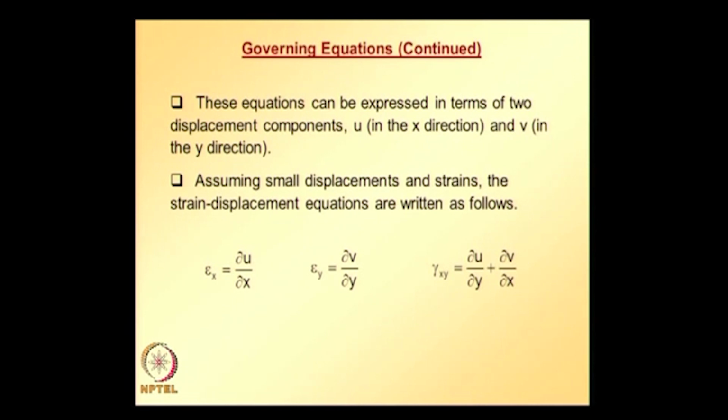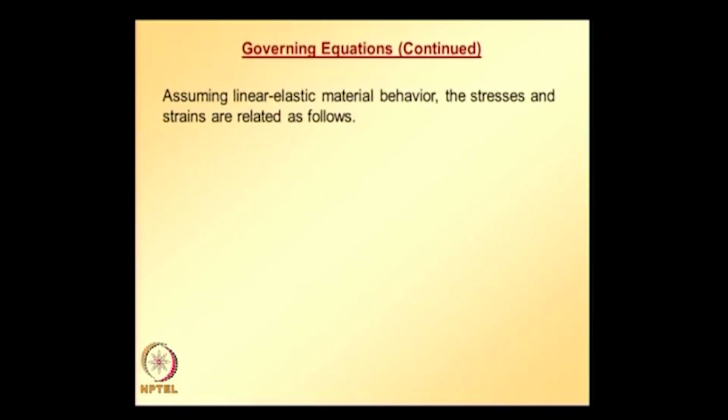We need to express them in terms of displacements. To do that, we first made this assumption of small displacements and strains, and based on that we got relationship between strains and displacements, and also under linear elastic assumptions, assuming linear elastic material behavior, stresses and strains can be related by these three equations.